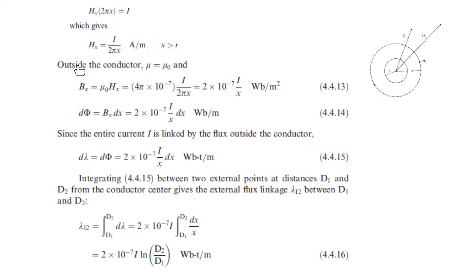All right, then we go on. And these are derivations, so you can go on again. Now we find this is the way. It repeats itself. From the magnetic field intensity, we get the flux density, and then the flux. From the flux, we get the flux linkage, lambda, as you can see here. If we divide by the current, we get the inductance.